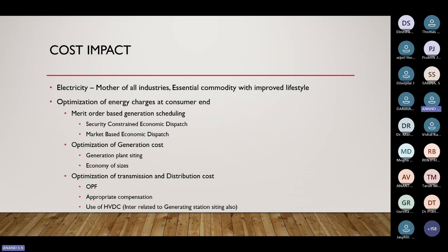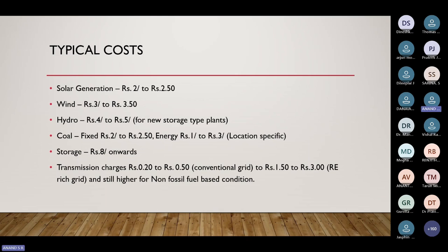But having a HVDC system with something like 100 kV or 80 kV to transmit something around say 200 megawatt or 100 megawatt, those systems are also being developed, and some of the prototypes are already there. Some installations have already come, and in commercial parlance, it is called light HVDC. So that is also another option which we are thinking about.